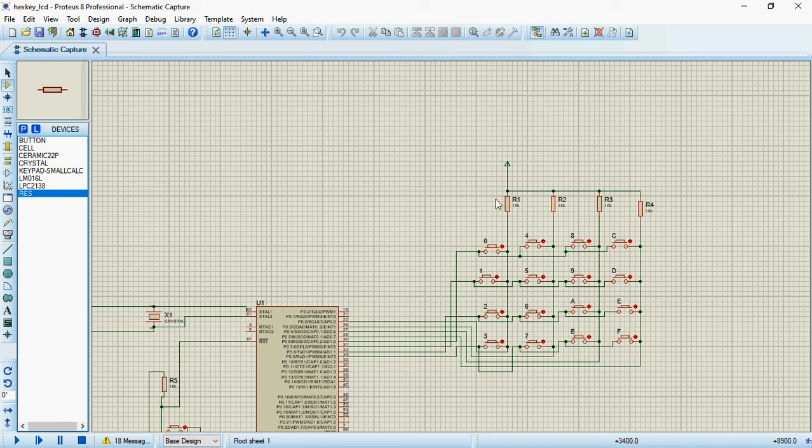Okay, and once it has been connected, one end of the button has to be connected with the help of a power supply. You have to use a resistor, and it has to be shorted. One end of all the switches are connected, that is on this column all switches are shorted. Similarly over here, all one common end is shorted, and it is provided with the supply voltage with the help of a resistor. So same has to be repeated for other columns. So on the row side, the one more terminal of every button has to be shorted up.